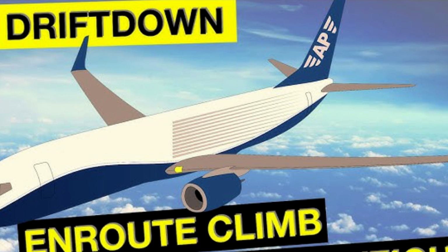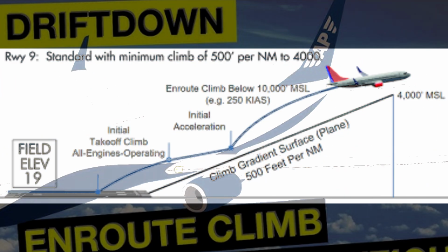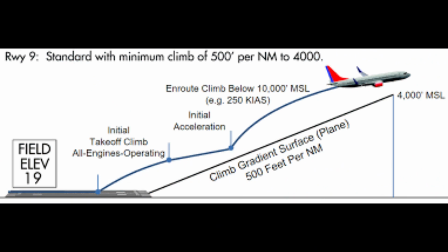Center then informed the pilot that there was traffic at 12 o'clock and a mile at 6,000. After passing traffic, a higher altitude was assigned and climb resumed. The pilot then believed the clearance was probably reaching 5,000. Even the readback to the controller with leaving did not catch the different wording. Reaching and leaving are commonly used ATC terms having different usages. They may be used in clearances involving climbs, descents, turns, or speed changes. In the flight deck, the words reaching and leaving sound much alike.